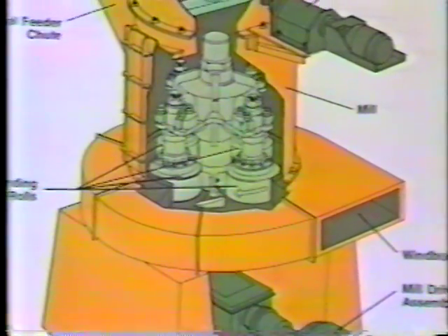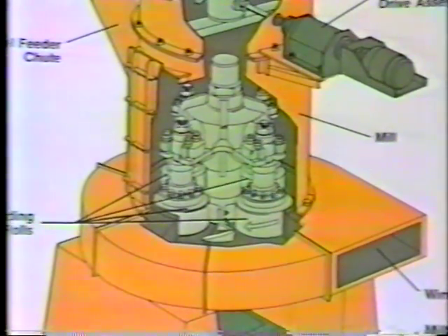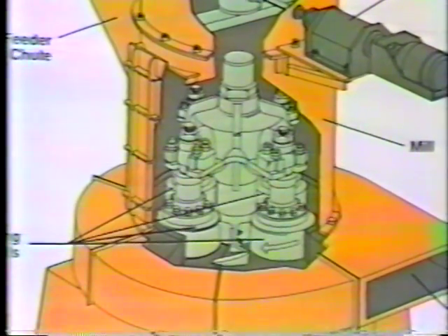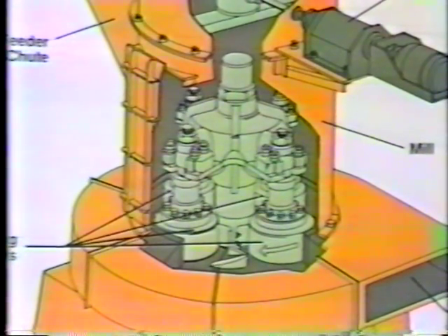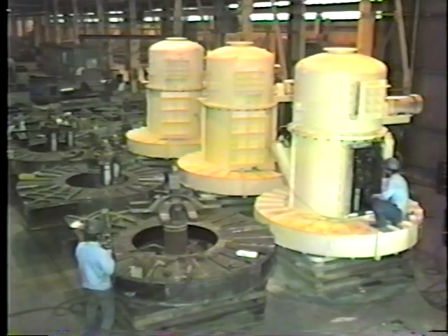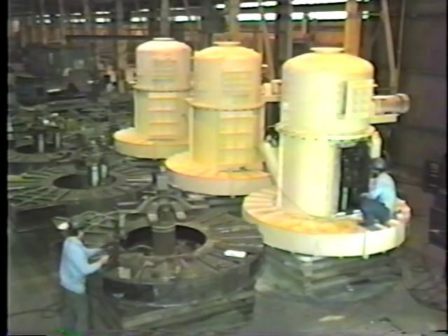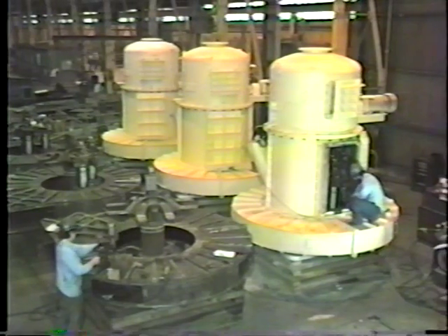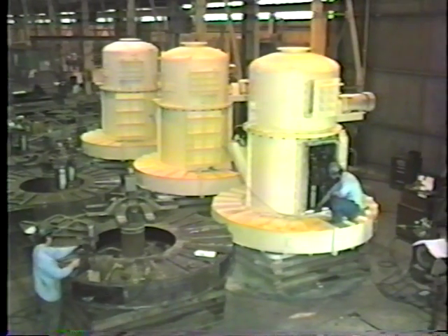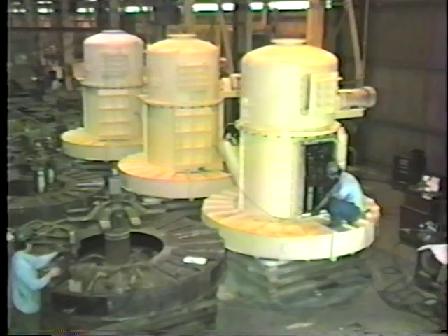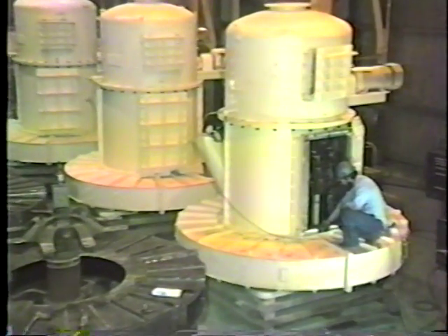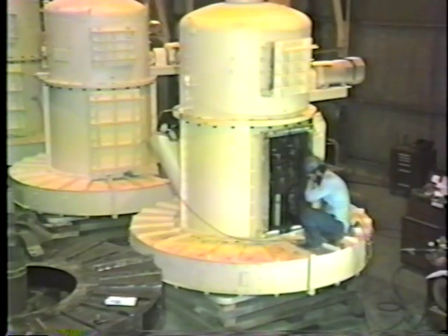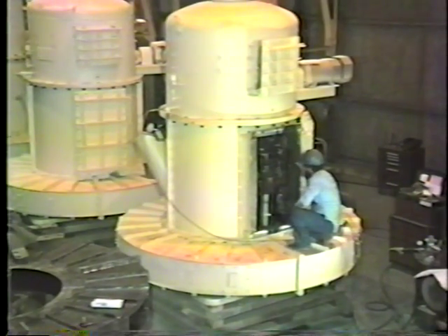The pulverizer cross-section, shown here, has a large access door through which journal assemblies are easily removed for yearly maintenance. So that we can better understand the overall mechanical function of the DF mill and their lubrication requirements, we show here a shop view of 6 mills under construction at our plant. The mill to the left has its cover and journals removed, while the mill to the right is complete with spinner separator.